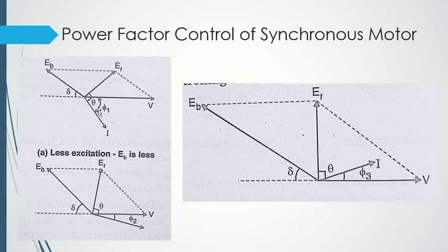Why am I saying that? See, what is power factor? Power factor is the cosine of the angle between my voltage and current, right? So it is basically cos phi, sorry, not cos into phi, it is cos phi. Okay, so if my angle is higher, let's say phi 1 is a very high value, and if you remember the table of cosine, as the angle increases, the value of cosine moves towards zero. And as it moves towards zero, your power factor will be less.